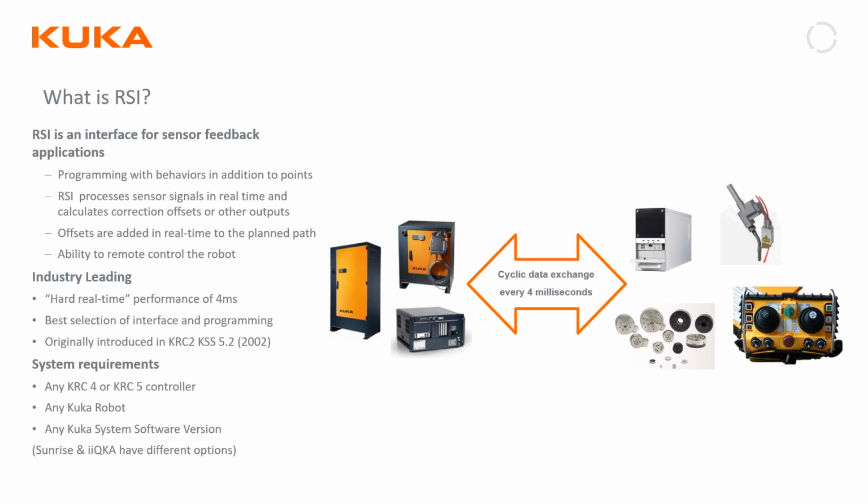RSI is an interface that gives the ability to incorporate real-time sensor feedback into your robotic application. Any sensors that can be connected to the I/O system can be used, and it also has interfaces that enable remote control of the robot by other systems or devices. This opens the possibility to program with what I would call behaviors, in addition to program points.